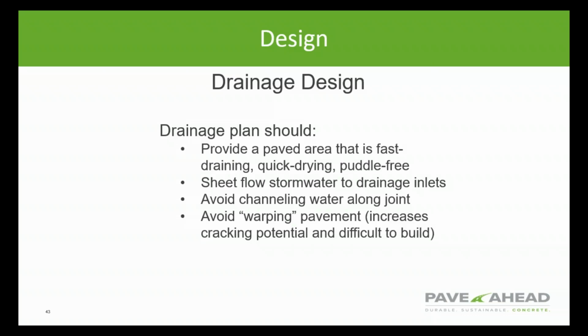So it's important that the sites are designed to ensure drainage of the parking lots, minimizing any type of ponding opportunities. Drainage plans should be coordinated with the jointing plan, and that's going to help avoid having water channel over the joints.